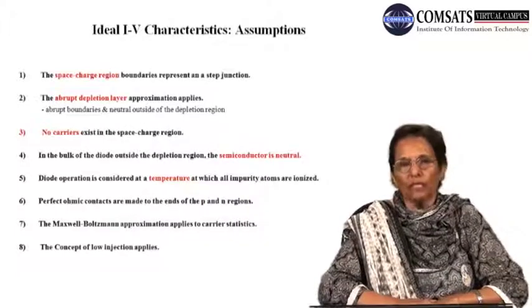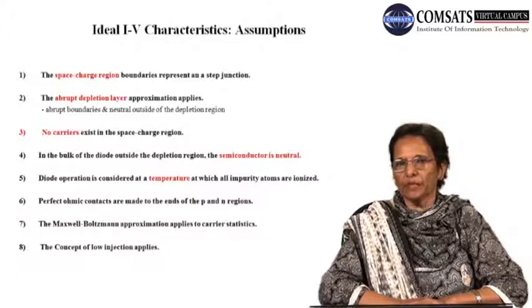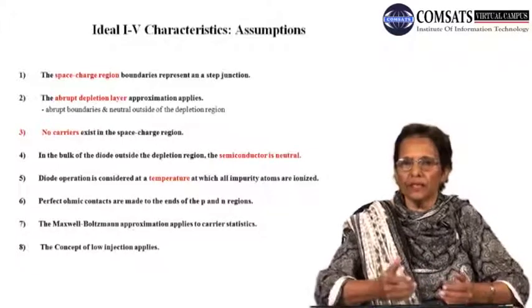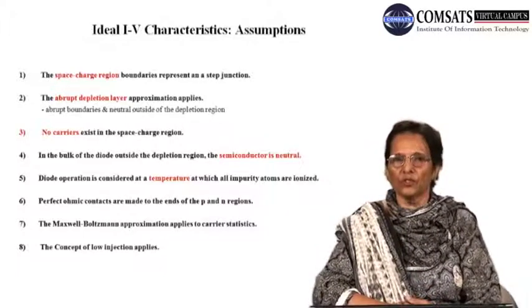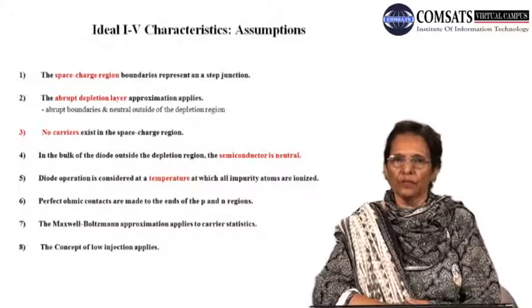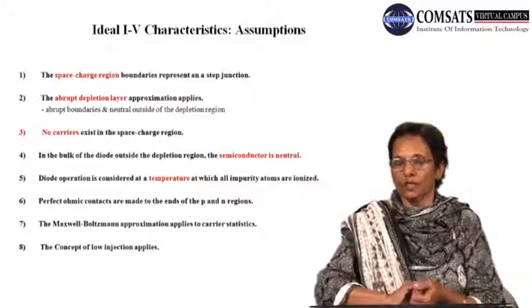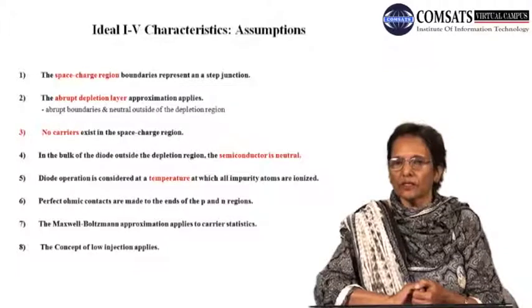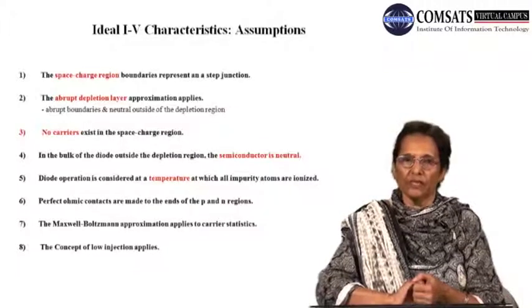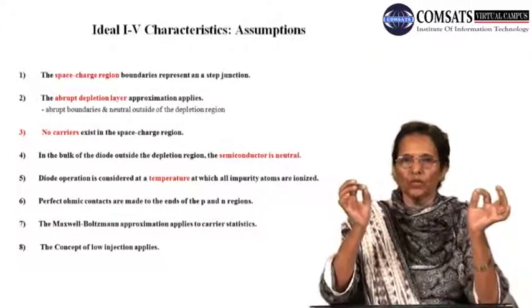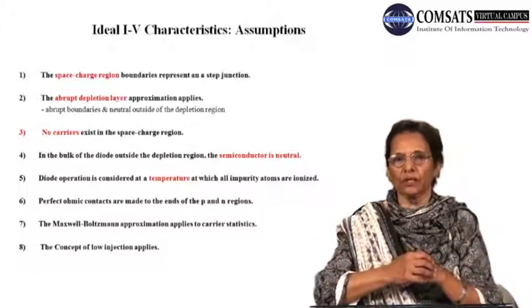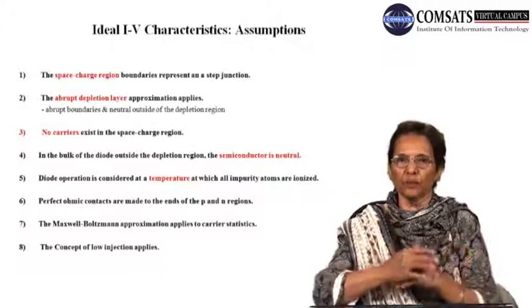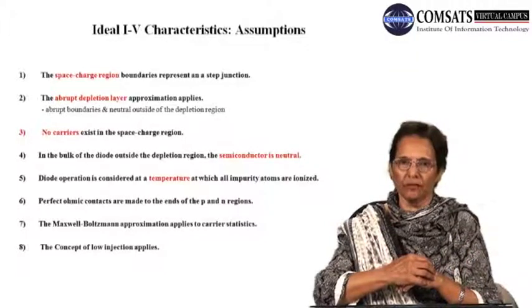And obviously, as we mentioned in our earlier lecture, the operation of a semiconductor diode, the current flow, the carrier concentration, and hence the magnitude of the resultant current, is very strongly dependent upon temperature. We even mentioned in our first introductory lecture that semiconductors at 0 Kelvin may be classified as insulators. They are termed semiconductors at a finite temperature, which in this course we have taken as a reference point to be room temperature, which is 300 Kelvin.